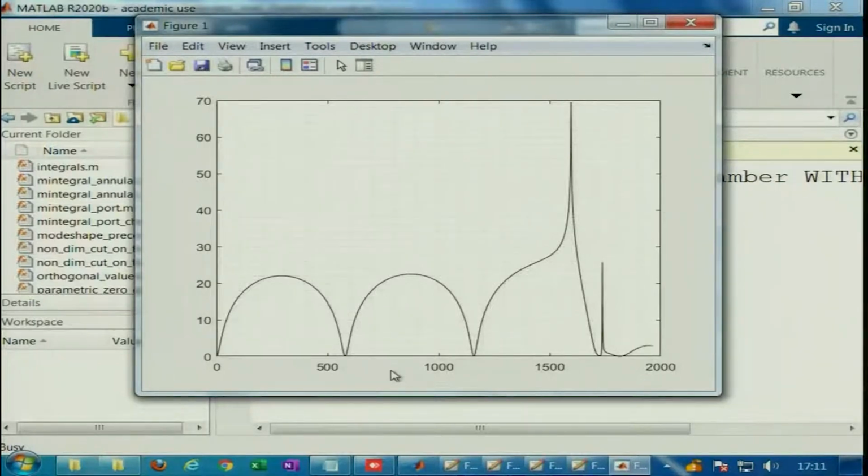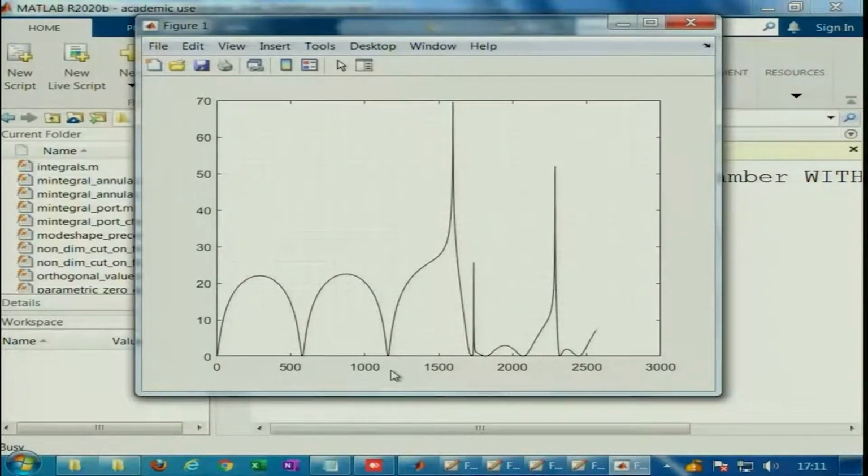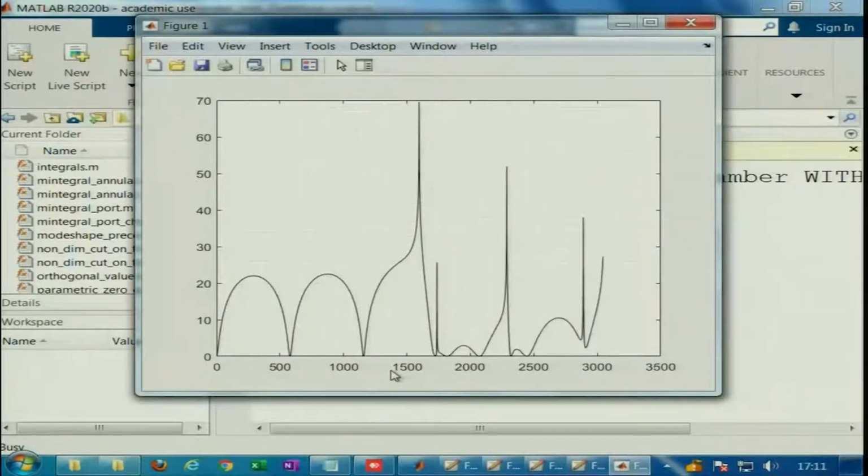Okay. You see a massive spike, and after that the behavior will be completely peaky, that there will be a large number of peaks, and basically once you allow the higher order modes to propagate, it will be a bad thing, because it will almost kill the transmission loss performance, and that is what is happening here. There will be a number of domes, troughs, peaks, a mixture of that, but this dome and trough behavior is still better than this part, because essentially once you have the higher order mode propagating for a simple expansion chamber muffler, the muffler is almost transparent.